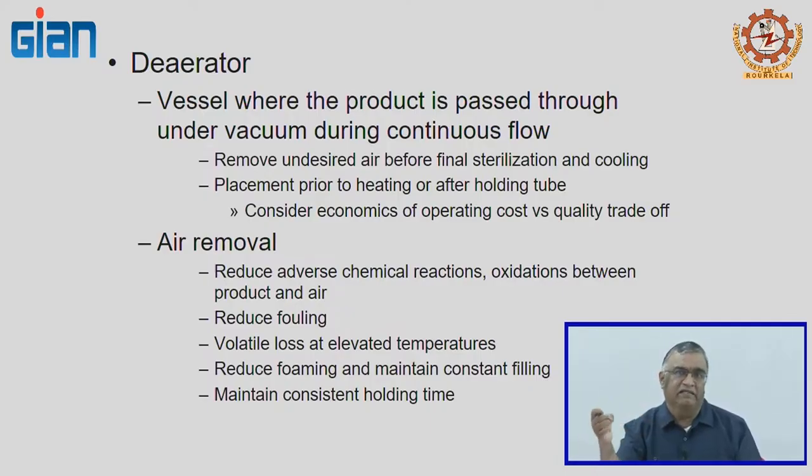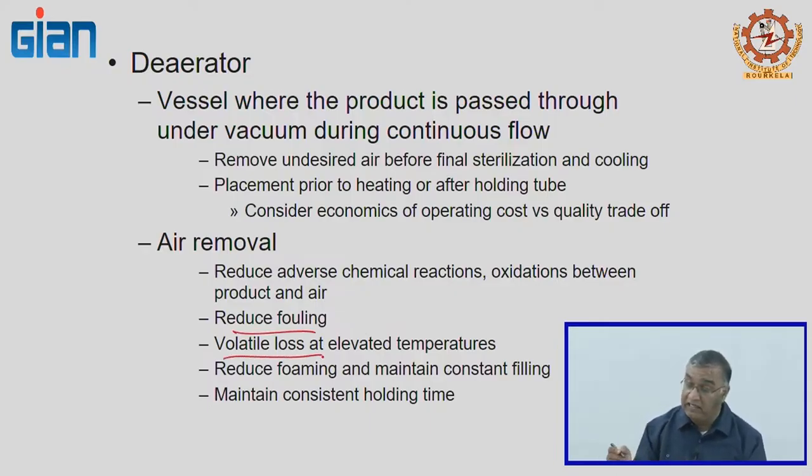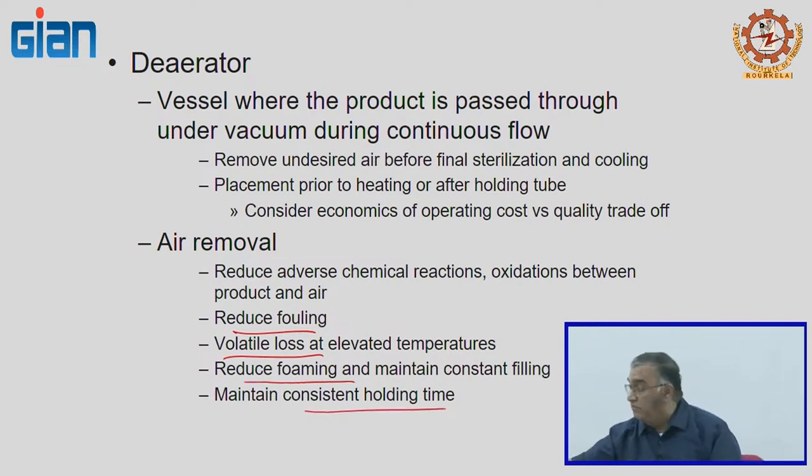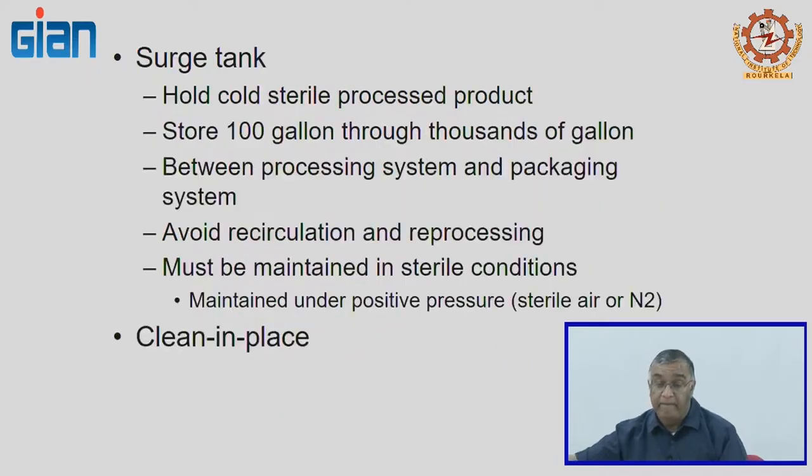The other thing is, air also has oxygen. When you store the product for a longer time, oxygen can affect the shelf life and quality of the product. So, you add a deaerator so that you can remove the air, and it helps to reduce fouling, reduce volatile loss, reduce foaming, and then you are able to maintain a consistent holding time under those conditions.